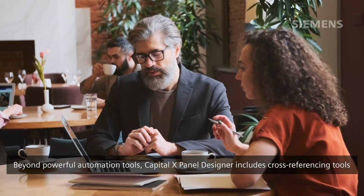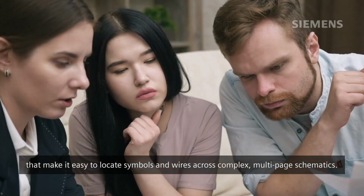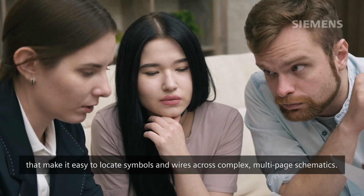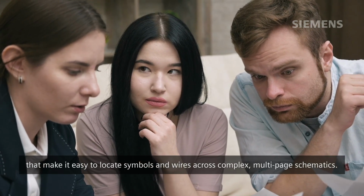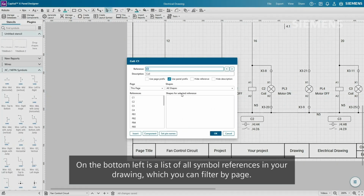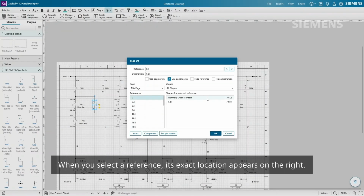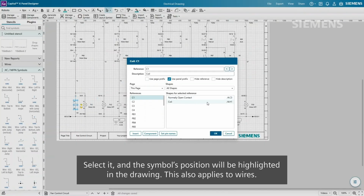Beyond powerful automation tools, Capital X Panel Designer includes cross-referencing tools that make it easy to locate symbols and wires across complex multi-page schematics. To access real-time cross-reference information, right-click on any symbol and select Edit Reference. On the bottom left is a list of all symbol references in your drawing, which you can filter by page. When you select a reference, its exact location appears on the right. Select it, and the symbol's position will be highlighted in the drawing. This also applies to wires.